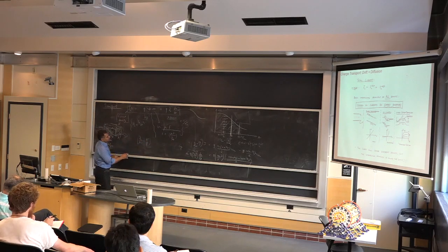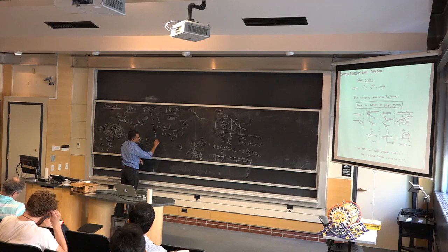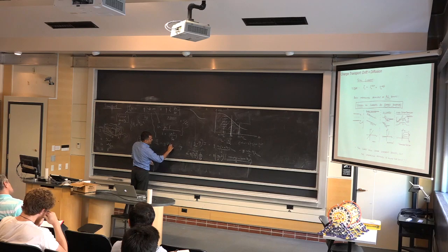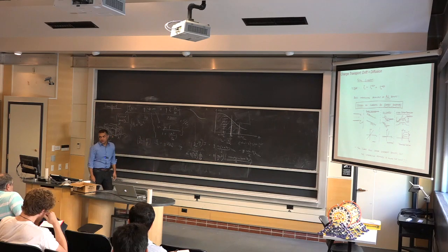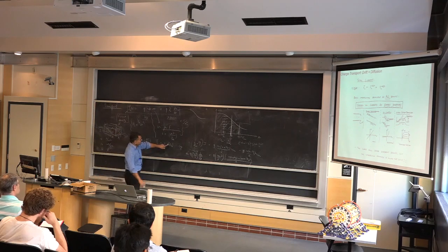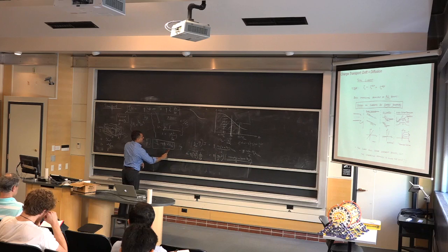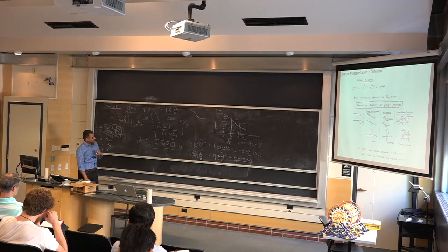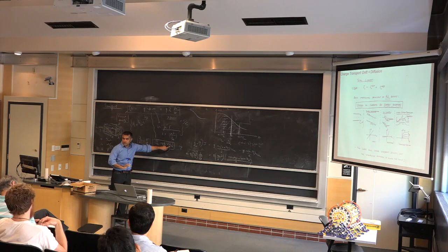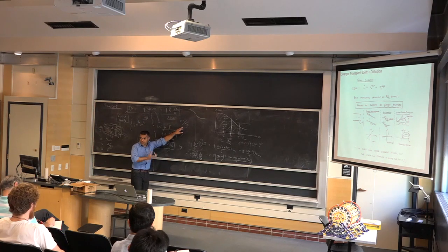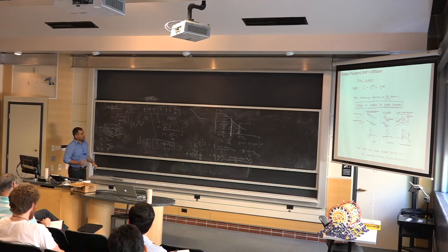The most general relation is basically that current is a vector, given by Q times the diffusion coefficient times the gradient of what you call the quasi-Fermi level, and we'll see that when we work through the currents. That is a representation that if you perturb the system, you apply some voltage or heat or light or something like that, you always change the Fermi level. And from there, all these terms emerge. So that's the heart of the problem, the way we understand transport, and we'll see that.